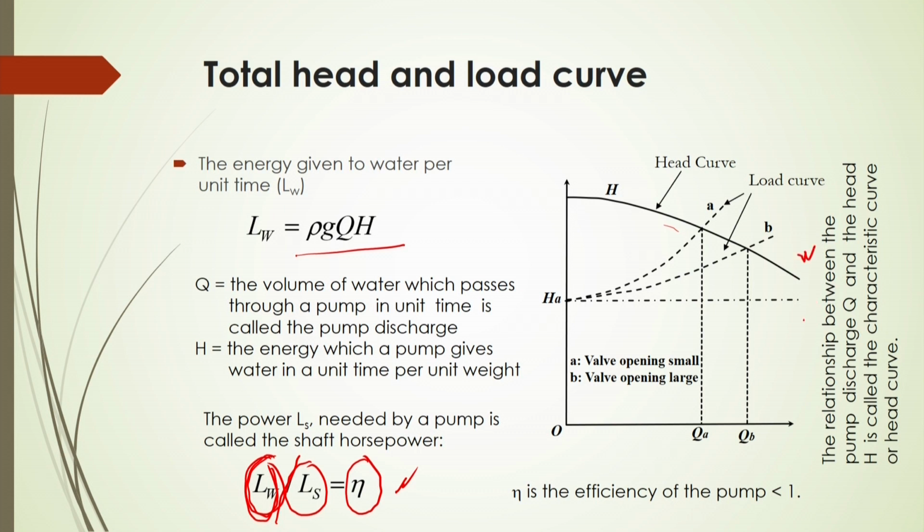So, as the load of the pump increases, you will see that the head curve will be decreasing as the volume of water per unit time increases. You will see the load curves here for A and B, A for a small valve opening and B for a large valve opening. For the small opening of the valve, you will see a higher load compared to the large opening of the valve.